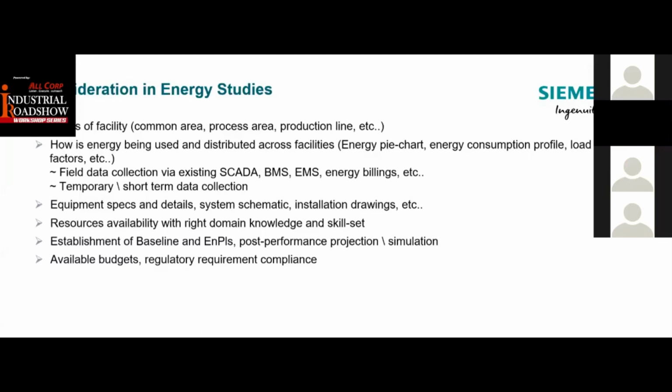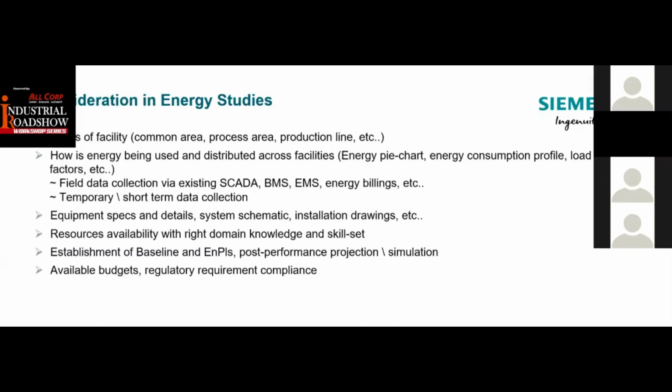And with all this information that you want to collect, what we are trying to establish is what we call the baseline, the point of reference, and also understand how the energy is being used and distributed across the facility or the production line. From all this data, you also get an indication of how the system performs when it is subject to certain loading conditions, and that's why we establish the load factors. And also at times we look at when the load is at a certain level, how the equipment reacts. So this will be the study carried out to help us understand the equipment better, and then find the best way to actually operate the system.